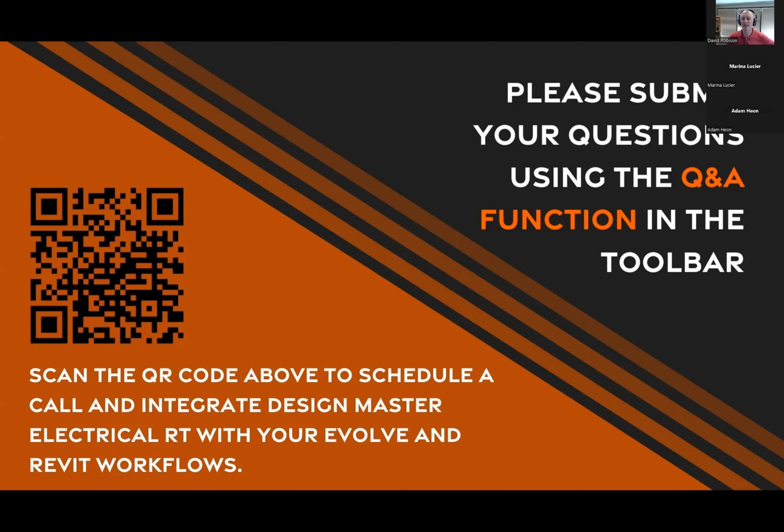But we fill in the estimated length with the values from our software. So this is what our software thinks they are. They're obviously not the modeled values. Those are being provided by Evolve. But we do export those if you want to have them in your feeder schedule. And on the Evolve side there, we do have through the Evolve reports a mechanism to compare estimated versus modeled. So you could always run a report after this once everything is updated to compare those. And then if there's any that are way off on a feeder where it's going to matter, you can then pull that back into Design Master with a fixed length at the moment.